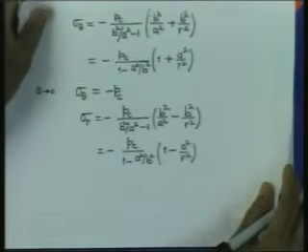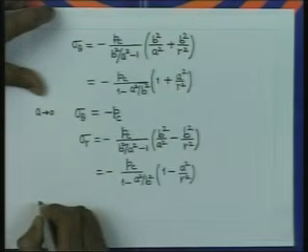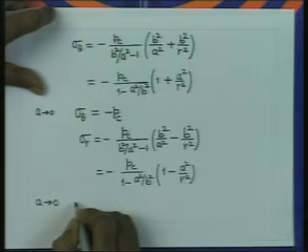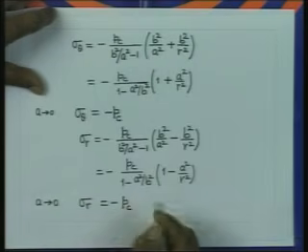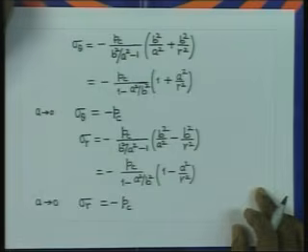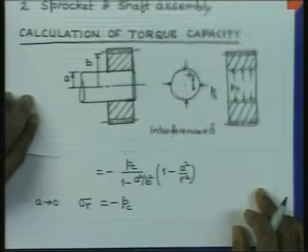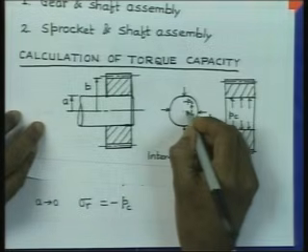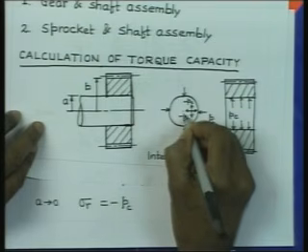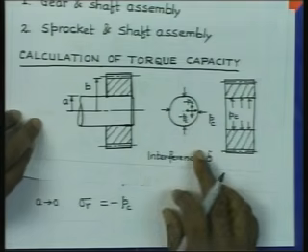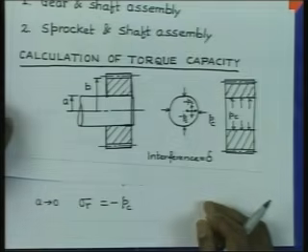And then if we shrink the dimension A to 0, make it a solid shaft, then in that case sigma r is equal to minus Pc. So, the stress not only at the outer surface is minus Pc in the radial direction, it is anywhere over the whole cylinder is going to be minus Pc. So, therefore, the stress in this direction is also minus Pc. So, this is really a state of hydrostatic compression at all points in the solid shaft.